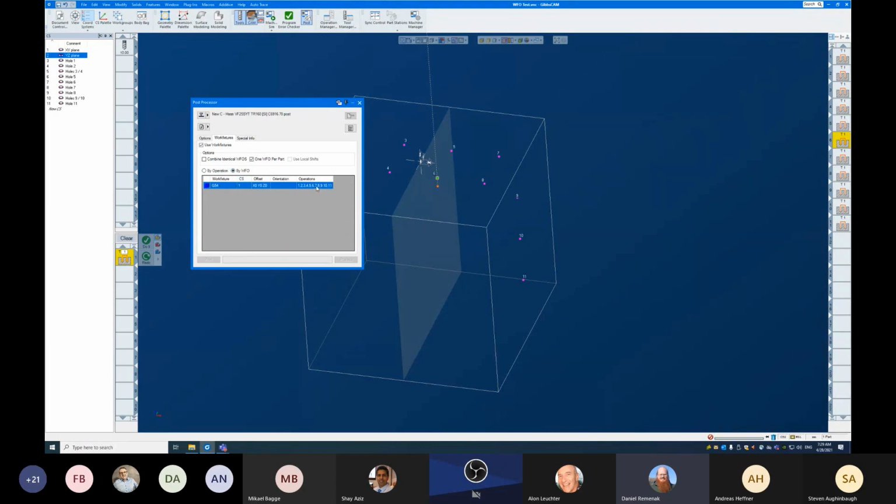So if you want to change the number, which I think is what you're getting at, we've had a lot of customers ask for that. Like G54 is in use by a different part or something like that. I want to shift this one to a different number. It's okay that it's the part origin, but I want to use a different number for it. You will have that ability here. Okay, that's what I'm asking for. Thank you. I think that was one of the very first things that we heard from a customer that really hit us as like, oh wow, that was a really big oversight in the system. The fact that we will always use that first work fixture will create conflicts on the machine.